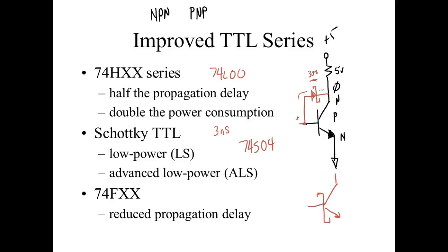It's gone. You can't hardly find standard series gates anymore because of the LS series. So we got basically the same performance. It was a little better. Rule of thumb propagation delay for standard series is about 10 nanoseconds. For Schottky, it's like 9. So you didn't get that much of a speed boost, but you did it at a lower power consumption.